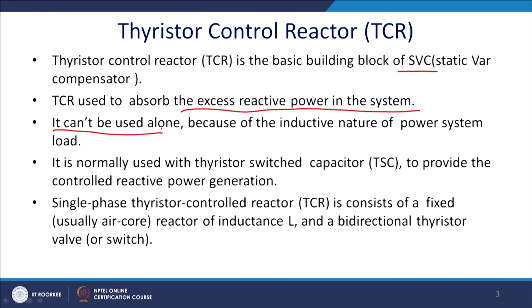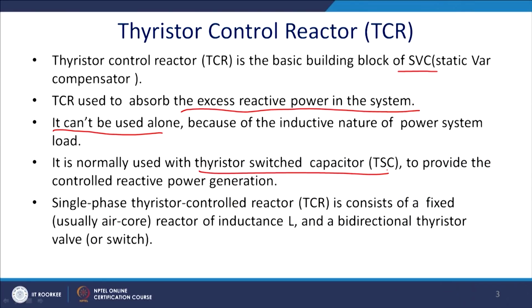Generally, it cannot be used alone because of the inductive nature of the power system load; most of the loads are drives based, and since these are inductive in nature, it is normally used with a thyristor switched capacitor to provide controlled reactive power generation.